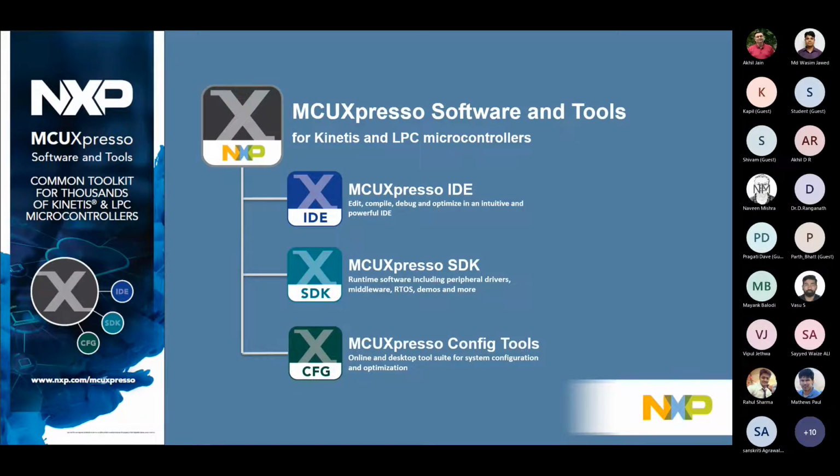And then to configure the MCU pins: in any MCU there will be different pins, and each pin will have multiple functions. Any pin could have ADC on it, the same pin can be made a PWM, or used as a comparator input, or in a GPIO, or for fault detection. But you need to first define which pin has to be configured for what function before starting your code.